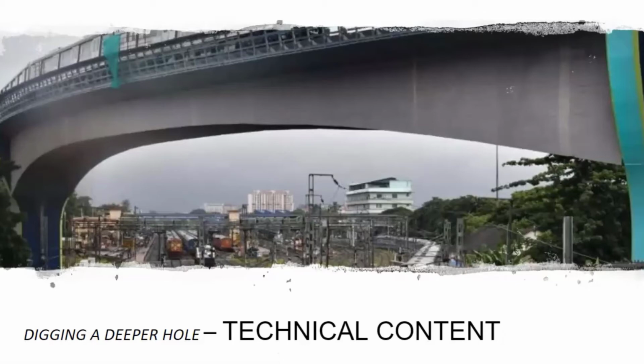For example, here you see a long span bridge. It has been built by a balanced cantilever technology, which is a relatively new technology. It helps us construct long span bridges, typically in the range of 60, 70, 80, 90 meters. And it also helps us span larger spans without disturbing the traffic below.